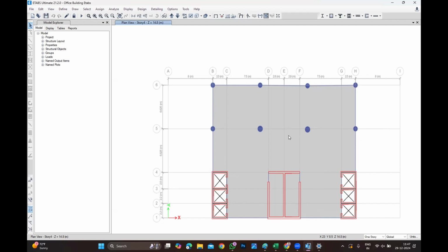Wind doesn't matter. Wind I can take; I know where the wind is going to go. If I have ring beams on top, it's easy because I know the concept. But this is what I achieve: a lack of stiffness, an exceeding lack of stiffness. We need to identify where the lack of stiffness will be, and on which floor the drift is going to be maximum. It is not that my drift is beyond the limit. I can go from the ground floor onwards, making all the structural stiffness elements massive.